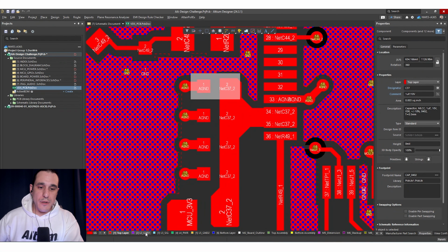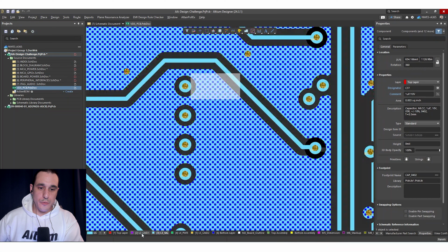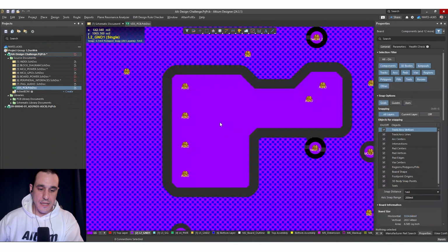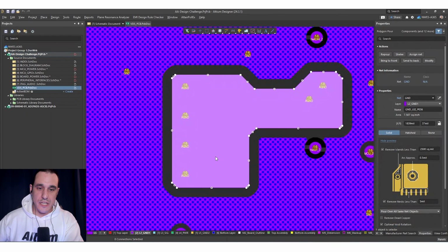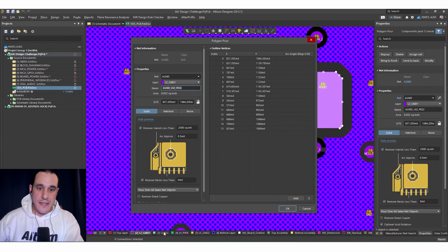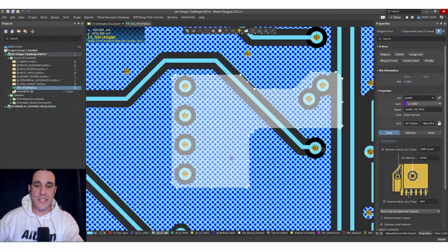The other reason I'm okay with it is because if you scroll through here on the internal layers and you just select this polygon, you see that there is really only one spot where I would recommend changing the routing, which is right here for this trace. This trace is routing over a split in this ground reference.